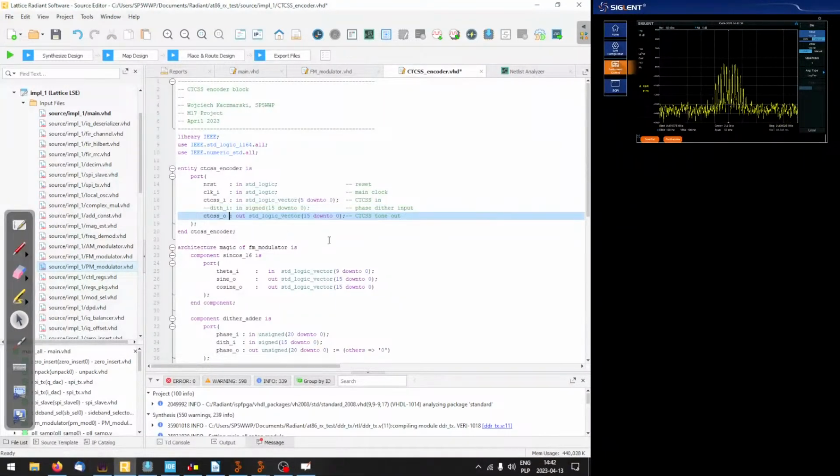All right, so that's much better. And that's, of course, going to be 16 bits. Even if we are going to use just 10 bits or so, we need this output word to be 16 bits because we are going to add that value to the value from the register number 9, and that's 16 bits. So we need this to be 16 too, to avoid resizing the vector later on in the main.vhd file.